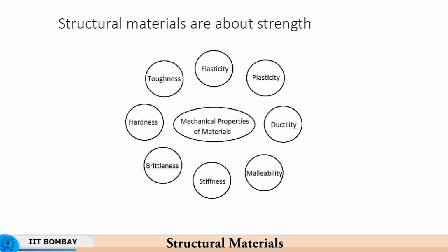You have these silver foils on sweets, extremely thin foils made of silver. Why is it possible? It is possible because of the very high level of malleability that silver has. The ductility of silver is extremely high, and that is why the malleability of silver makes it possible for us to make very thin foils which can go as decoration on the sweets.